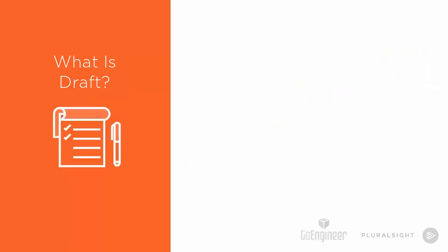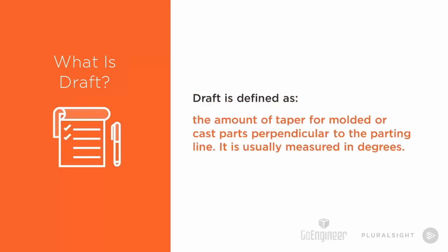So what is draft? It's the amount of taper for molded or cast parts perpendicular to the parting line, and it's usually measured in degrees.